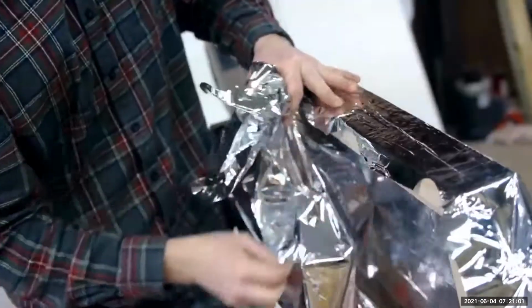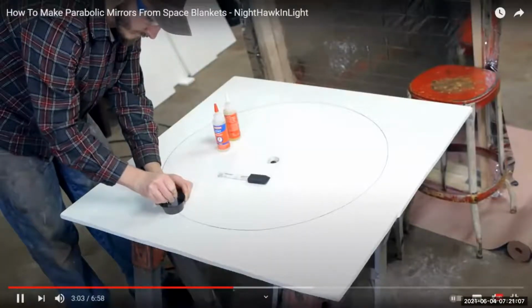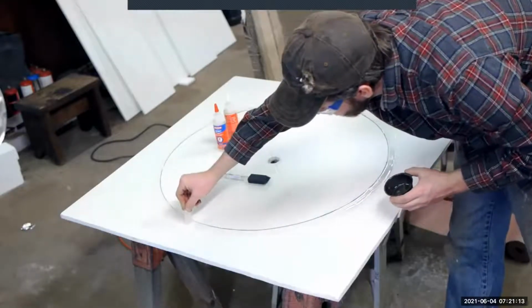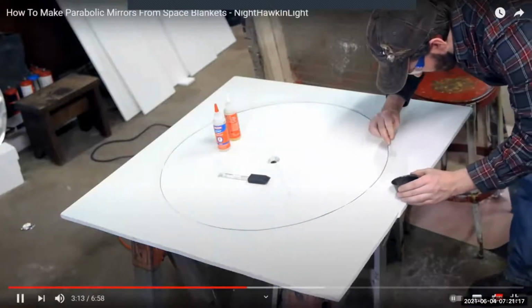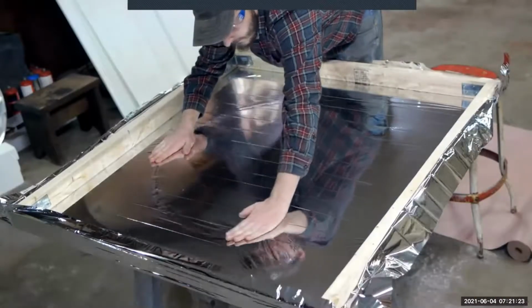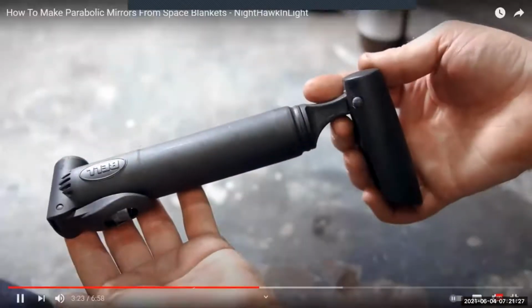The baseboard is prepared, and now so is the Mylar, so it's time to see if my method will work. From some tests I did earlier, I found that epoxy is the best adhesive for adhering Mylar to PVC, so I'll carefully spread a layer around the outline of the circle. The Mylar is then lowered on top and pressed into the adhesive to get a good seal. To provide air pressure, all it takes is a bicycle pump.